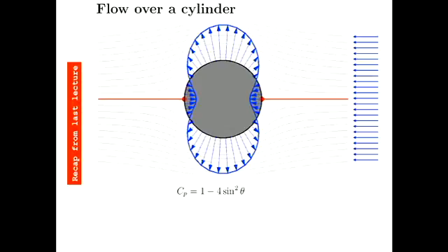And if we then wanted to build an aircraft that used that aerofoil, and that aircraft, say, had a weight of 2 tons, I'd know that I need to generate 2 tons worth of lift, and I could use that lift coefficient that you calculated from your laboratory to then scale that aerofoil, or work out how much area or what size that aerofoil would need to be in order to generate that lift for a full-size aircraft. So you're doing a scale model test to get that coefficient, and then you can use that coefficient at full scale to actually build something of use, all right?